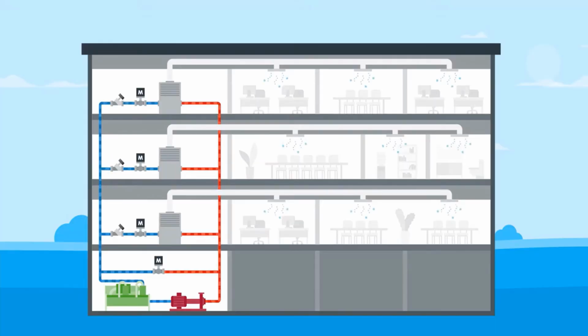So let's start. Here you can see it is a primary variable system. For any building to experience comfort and energy saving, it always matters what kind of pumping somebody has chosen for pumping the chilled water from one corner of the building to the extreme last corner of the building. So we started learning about the constant flow system, primary variable, primary secondary variable system, and in this video we are going to experience the distribution system: what is this distributed pumping system and how it needs to be configured and designed.